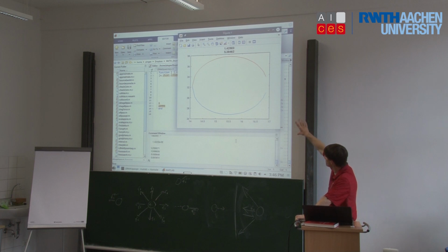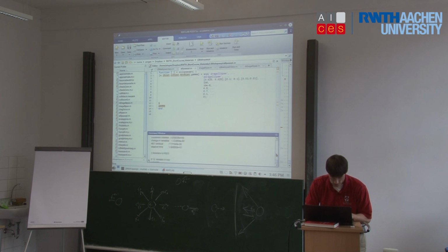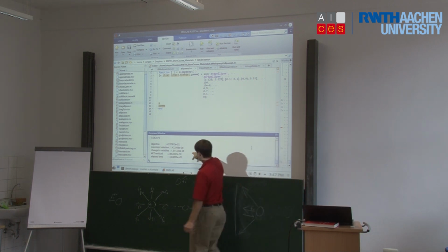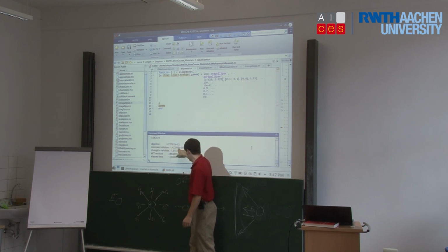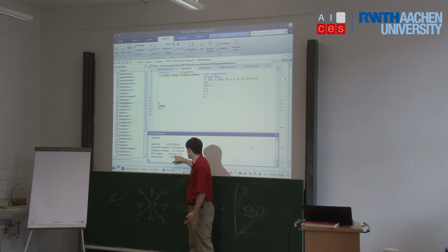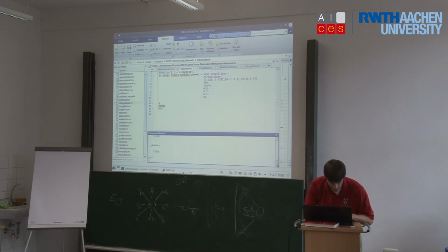Okay. So this is converging now. We can actually see, at every iteration, it prints out some basic information. The objective, the constraint violation. So basically the constraint is satisfied. How much have the design variables changed from the last step? Basically not at all. So this is a KKT residual. Okay. Well, I guess this is actually the final result. So we have converged at this point. The residual is minimal.